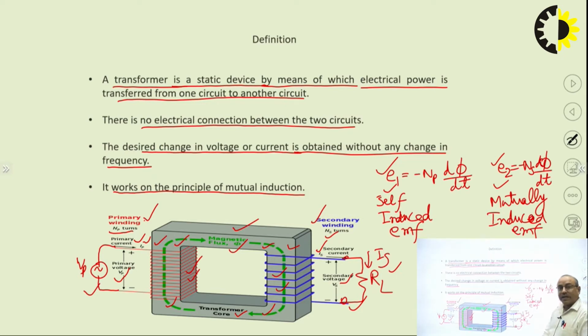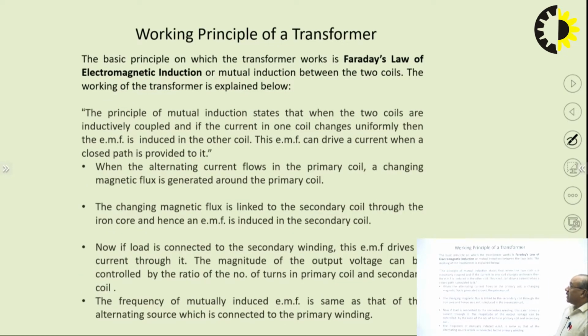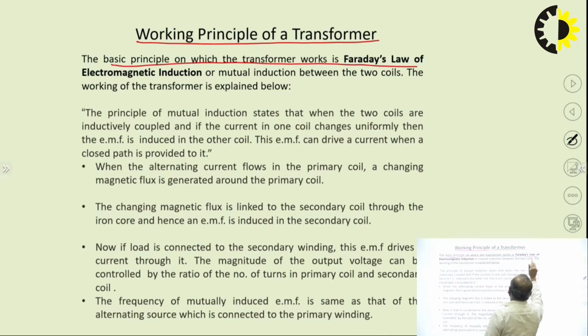If we see it further in detail, the working principle of a transformer that we have already discussed: if we elaborate it further, the basic principle on which a transformer works is Faraday's law of electromagnetic induction, and basically it is mutual induction, since in the secondary the EMF is induced due to the mutual induction process from the primary side. So, this is mutual induction between the two coils or windings, primary and secondary.